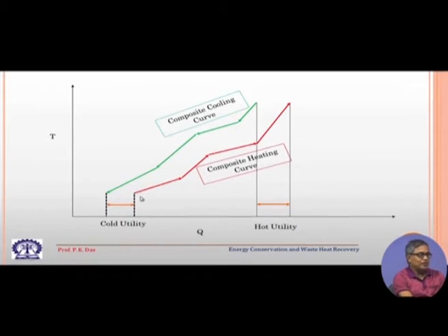these two super streams, because now it can be called a composite cooling stream or super cooling stream, and this is a superheating stream. So, even if we consider these two composite streams and heat exchange between them, we will not be able to bring all the hot streams to their target low temperature by this internal arrangement. So, maybe we have to use some sort of cold utility. So, this shows how much cold utility we need to use schematically.